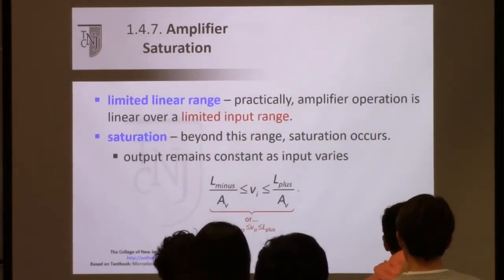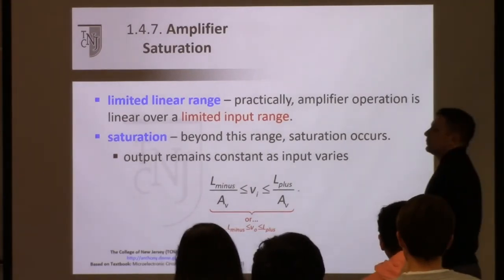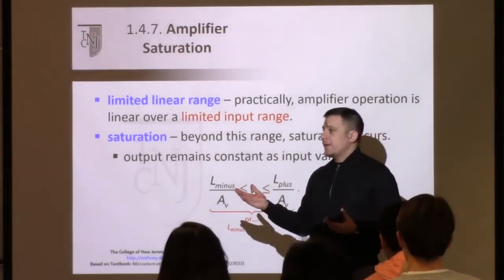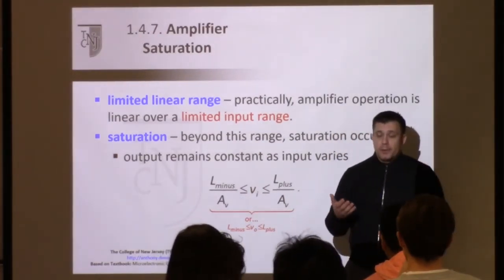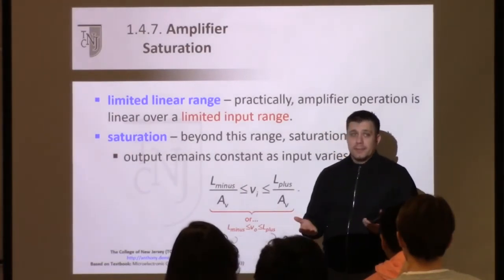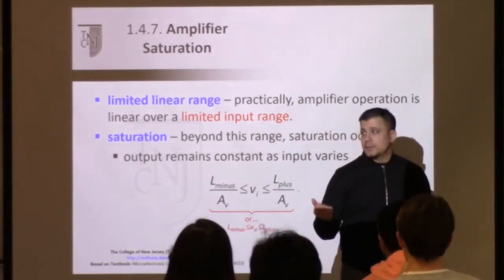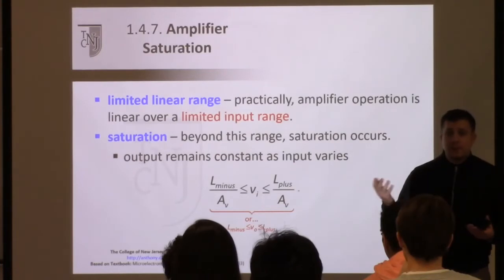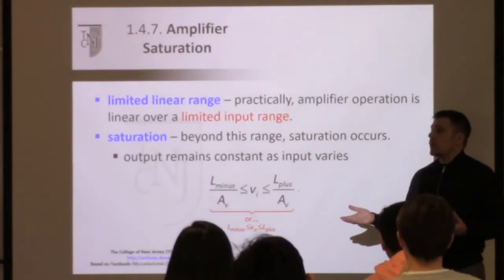Okay, amplifier saturation. This is one of the really comprehensible, non-linear behaviors that we see. You've already seen it. You saw it in ELC251 in the circuits lab. When you were working with amps in that lab, it couldn't work for an infinite range, right? There was a limit that the output worked on. What was it normally? Yeah, the supply voltage essentially dictated it. So we were often using like -15, +15, -12, +12, whatever that is. So the output of the amplifier couldn't go past that.